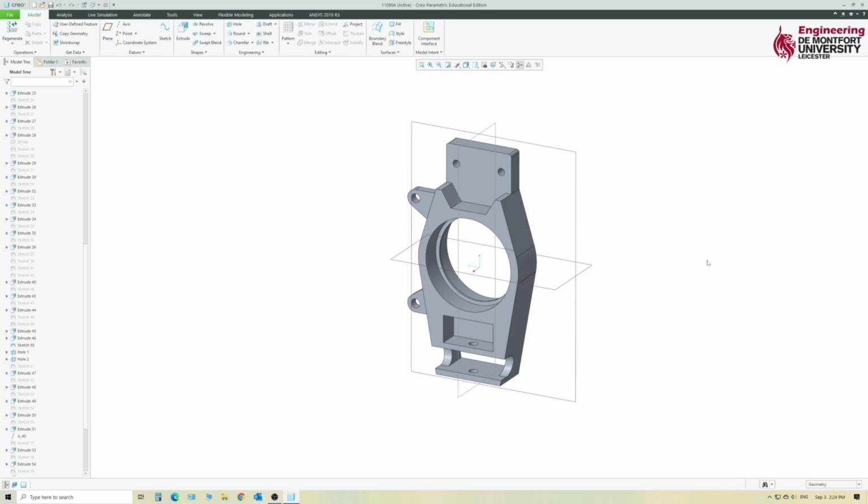In this video, we're going to be exploring how we can add additional datum planes to add what would normally be tricky geometry to a component. So here I've got a front upright assembly from the assignment, and I need to add the steering arm. Now it would be quite difficult for me to do, and take multiple steps, if I just use the current planes that are available to me. So I'm going to add a new plane.